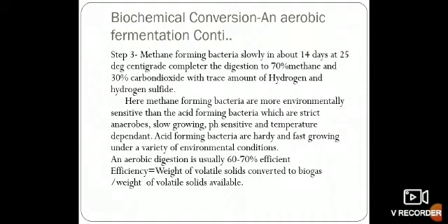Anaerobic digestion is usually 60 to 70% efficient. Efficiency of biochemical conversion is given by the weight of volatile solids converted to biogas divided by the weight of volatile solids available.